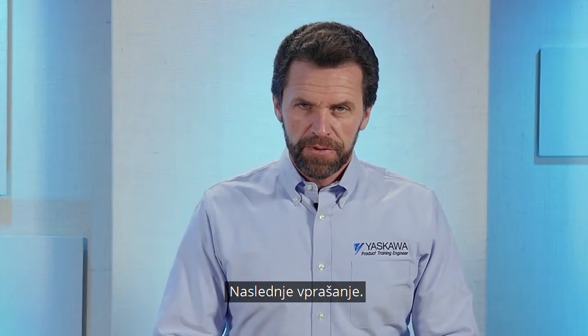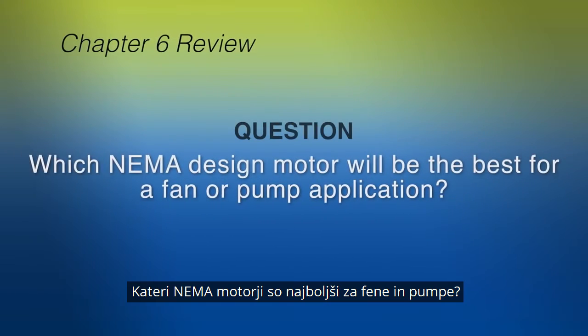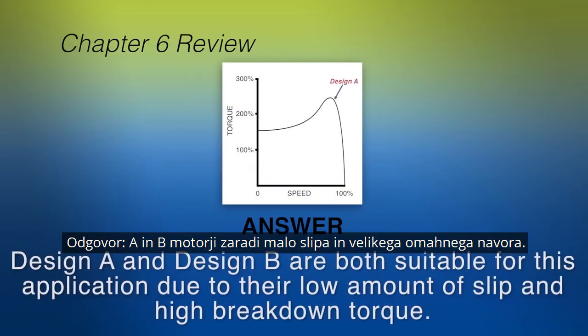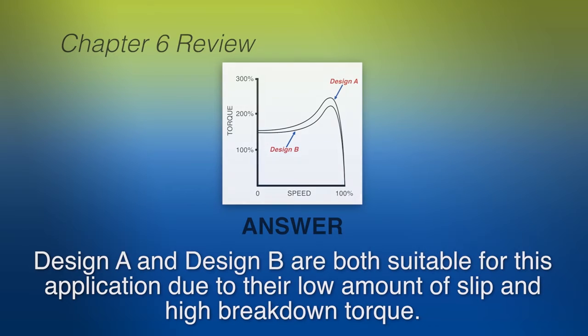All right, before moving on, here is another review question. Which NEMA Design motor will be the best for a fan or pump application? The answer? Design A and Design B are both suitable for this application due to their low amount of slip and high breakdown torque.